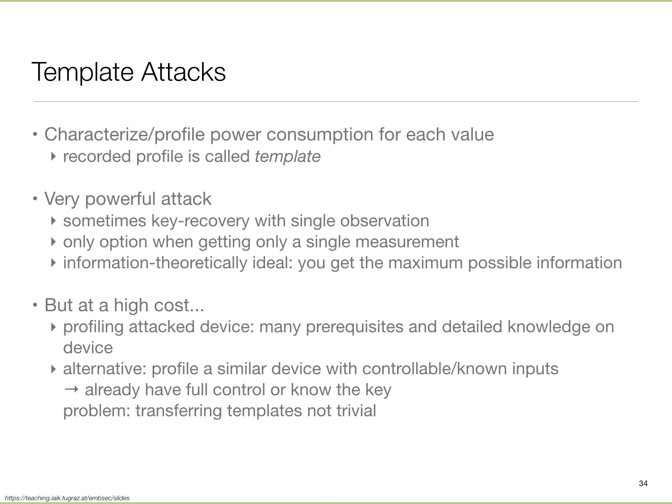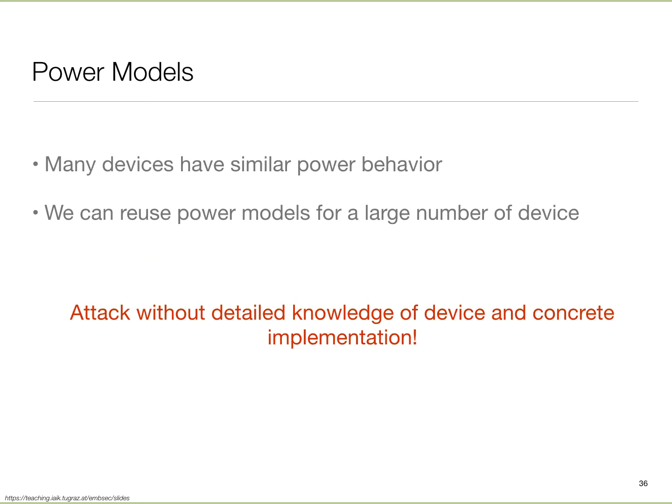So if I have an algorithm, I can run it under different input settings and find these traces. This way I could essentially develop an empirical model. For different parts of my function, I would say, okay, if the bit was 0, if the bit was 1, what does the signature look like? I capture it and I map against that. So that's one approach.